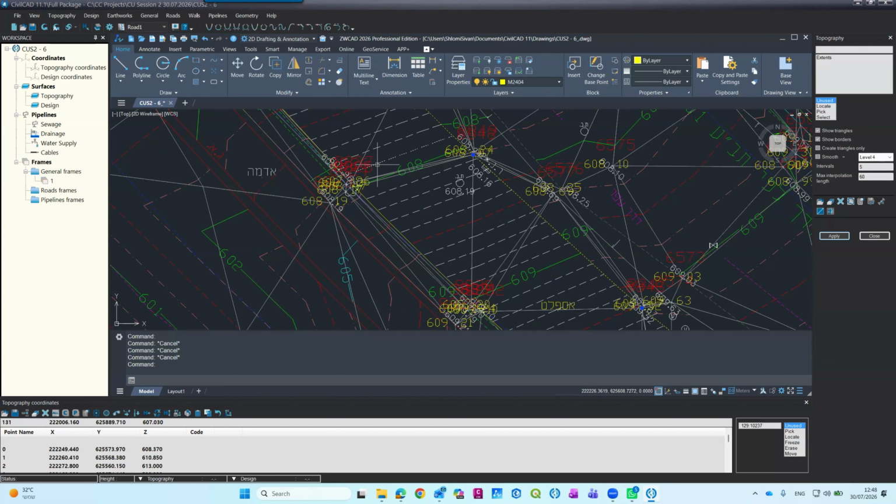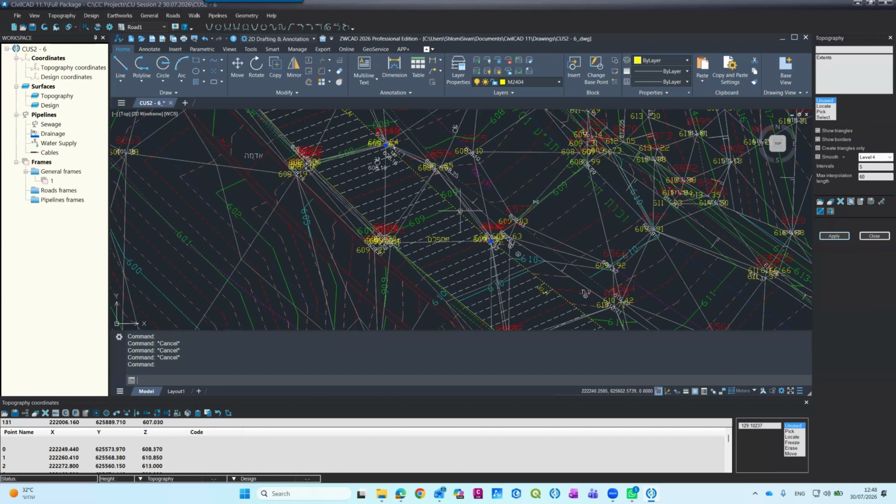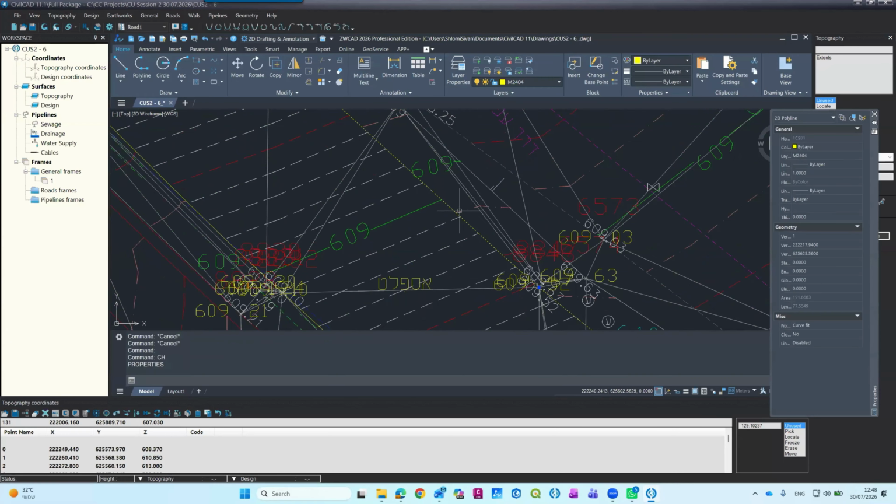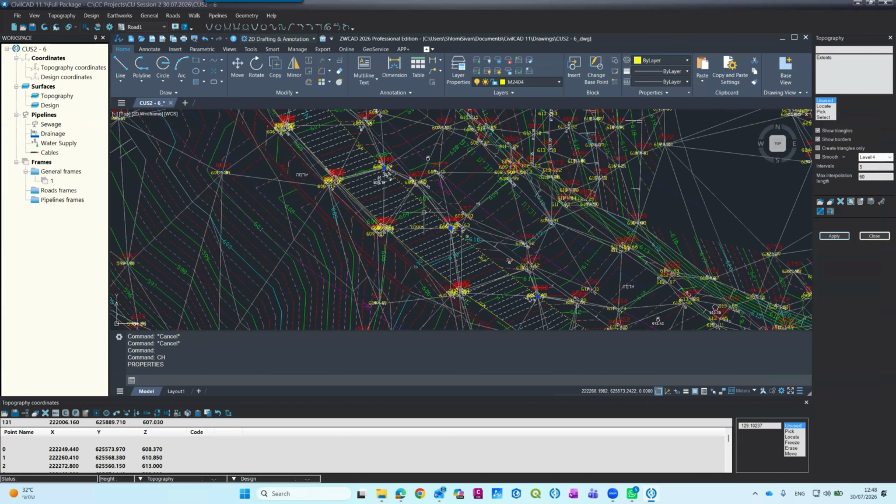M2407. What I can do, I can filter this as a breakline. But before that, I want to see if it's in 3D. Unfortunately, no. The elevation is 0. So if I would filter it, it will not give me anything. I cannot use it. I can take it and then project it into the elevation of the surface, but even then, it will not be truly accurate. So in this case, maybe since I don't have 3D lines that represent my break lines, of course I can create it myself, but if I want to use what is already on the ground, I can use another method.